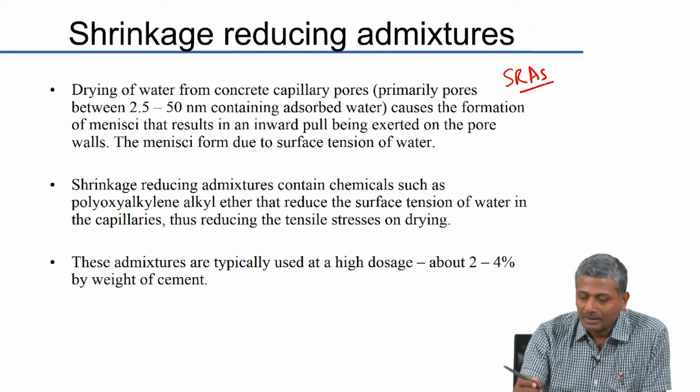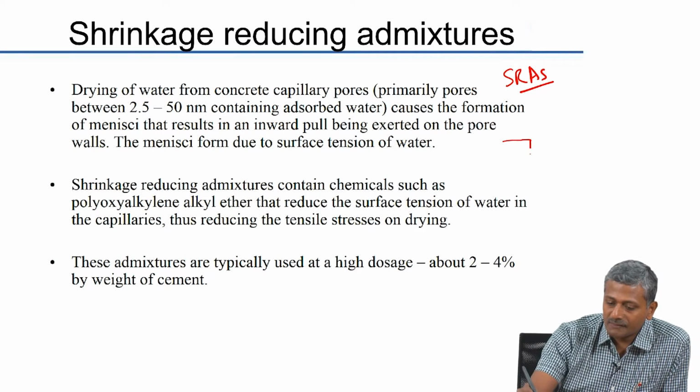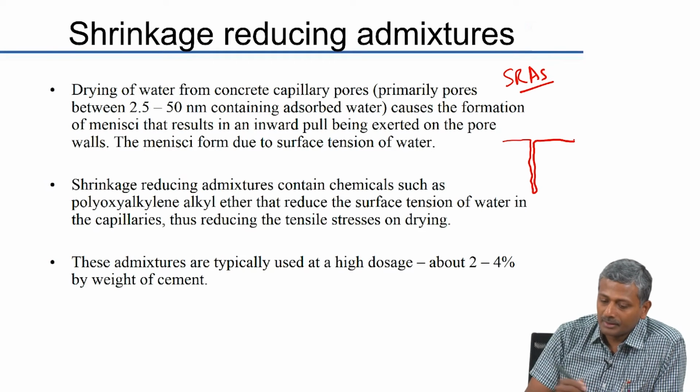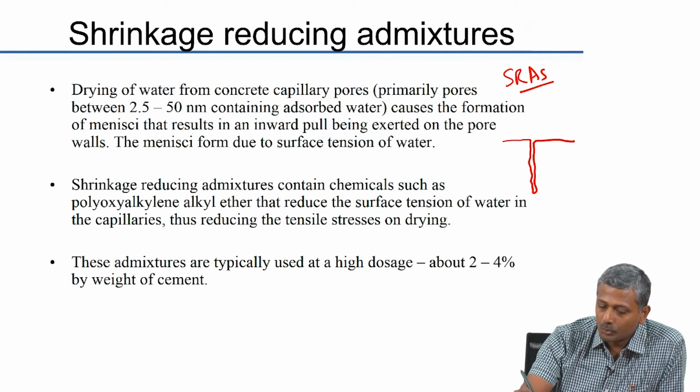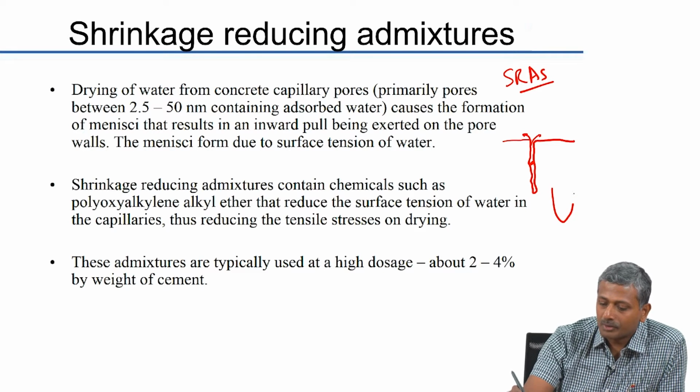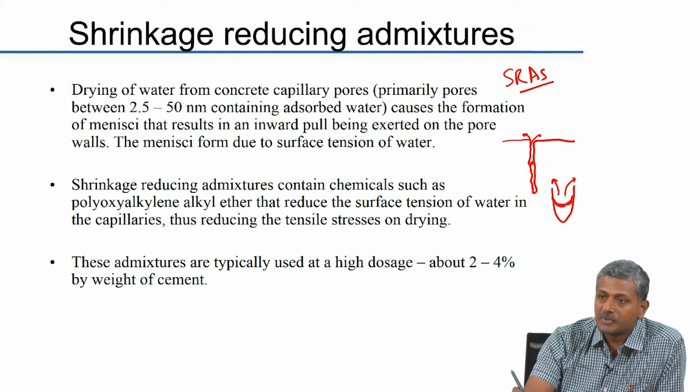So, just to look at a pore on the surface of the concrete, this is just an exaggerated view of a pore on the surface of the concrete. Okay, so, there is water inside the pore, and when this water tries to dry out, okay, let me just draw a magnified view of the pore and the water forming a meniscus inside the pore. Right, when water is drying out, it forms this meniscus inside the pore. Right, it forms more and more of a convex meniscus as it starts drying out.